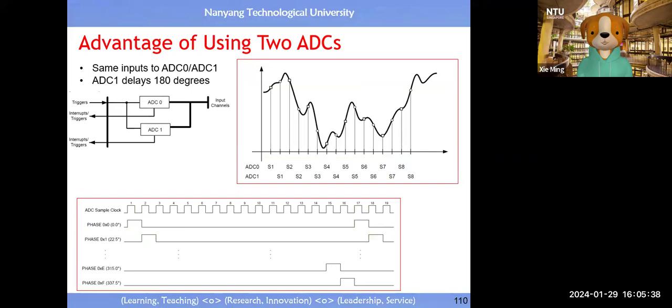Then, okay, the good news to you is you may have a single sensor, and you can double the resolution of doing the sampling, because with one quantization device, actually you can say you take one series of samples, and another one takes another series of samples. If these 2 series are offset a little bit, actually you double the number of discrete sample channels.